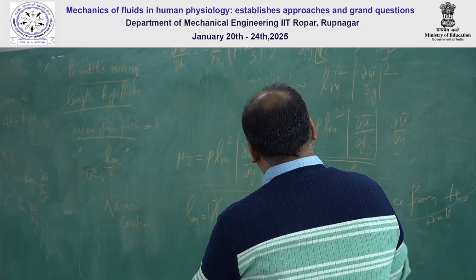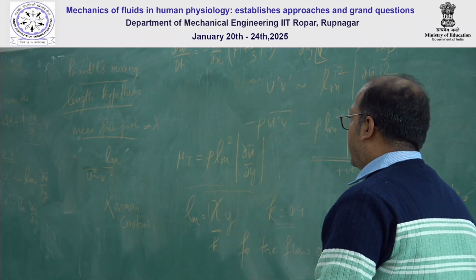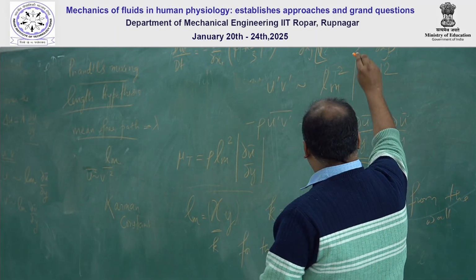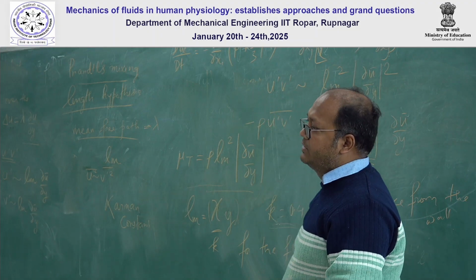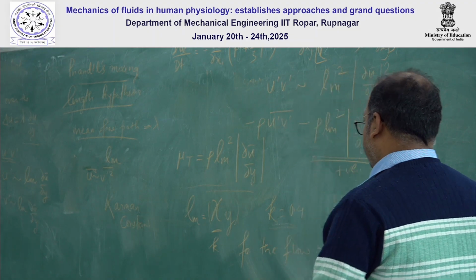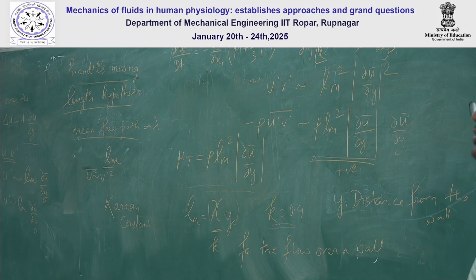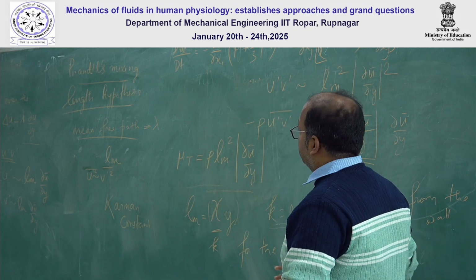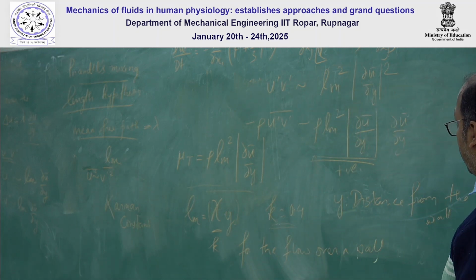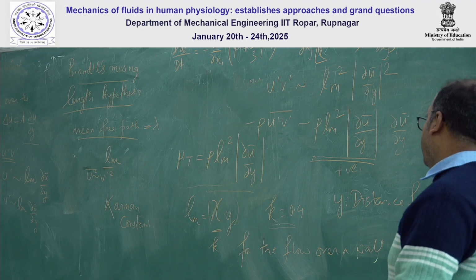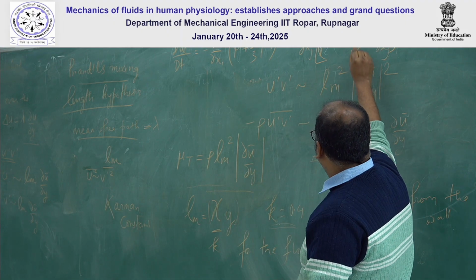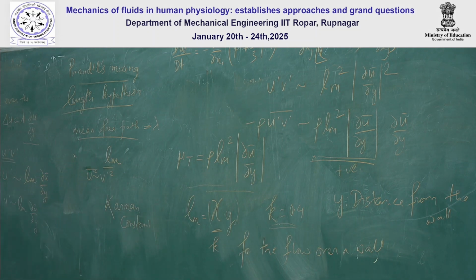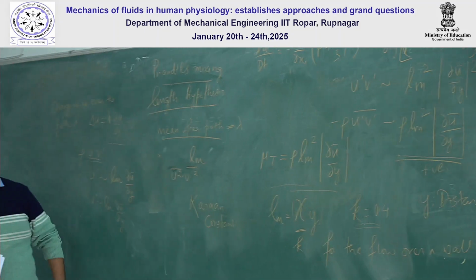Okay, so first we saw the turbulence closure problem. Then, in order to tackle the turbulence closure problem, Boussinesq floated the idea of turbulent viscosity. Basically, the Reynolds stress was decomposed, just like the normal stress component, into isotropic and anisotropic parts, and the anisotropic part introduced the concept of the turbulent viscosity mu t. Then, to get a quantitative estimate of this mu t, Prandtl suggested that we adopt the concept of the kinetic theory of gases. His hypothesis was the mixing length hypothesis.